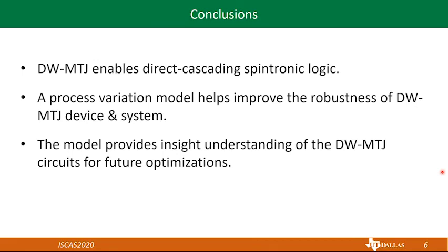So, conclusions. First, the DW-MTJ is one of the few spintronic devices for which direct logic cascading has been experimentally demonstrated without any external buffering or amplification stages. That enables purely spintronic non-volatile computing systems with no need for CMOS circuitry between devices.